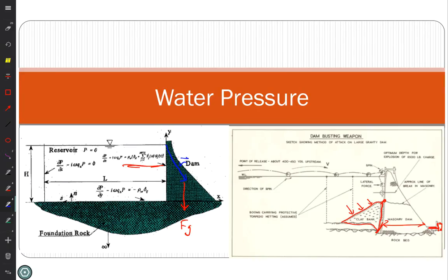More mass, because the force of gravity is on mass. Okay, more mass, yes, but there's another thing about where that mass is placed. Where's it going to be more beneficial to have the mass placed? Further out. Because the perpendicular radius is the radius that's going in the horizontal direction, because the force of gravity is down. So if that mass is further out, it's going to create a bigger counter torque to help compensate. So a reason to have it slope away is so you can get that counter torque there.